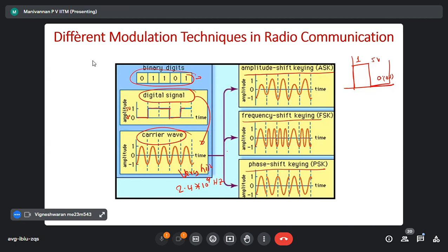Okay. Now, if I combine these two, it can be amplitude modulated. Please see that this carrier is a fixed amplitude. Correct? In this case, what is first this one? 0. Right? You are going to transmit 0. What happened? The amplitude of the carrier, see, this is the full height, half of the height only is transmitted. Correct? During this period, the carrier amplitude is reduced.